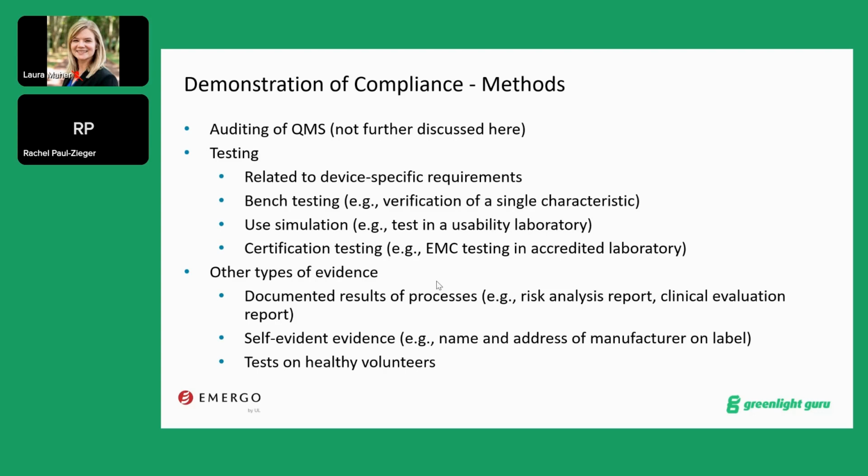You also have testing. You will develop testing of your device to demonstrate your device complies with a product-specific standard, for example. This may be related to device-specific requirements, to bench testing for verification of a single characteristic. It could be use simulation, a test in a usability laboratory. It could be certification testing, so EMC testing in an accredited laboratory. All are related to testing to generate test reports to demonstrate compliance.